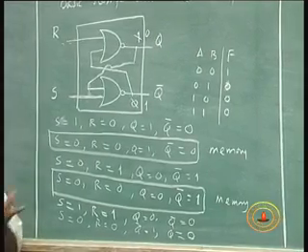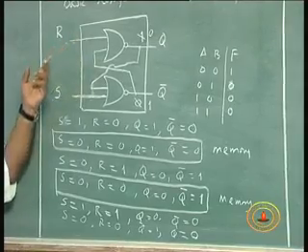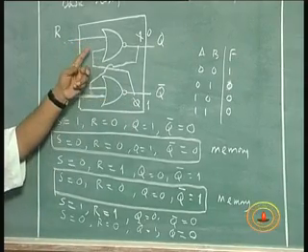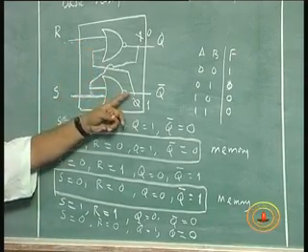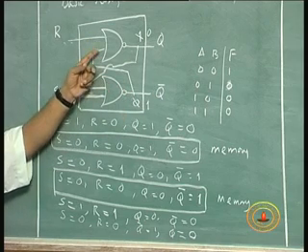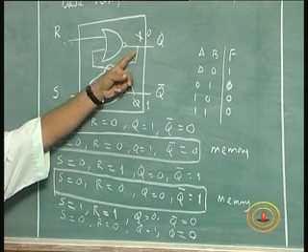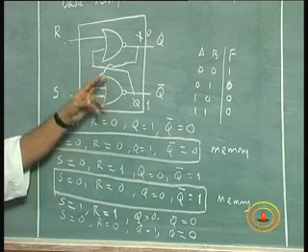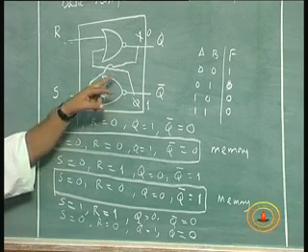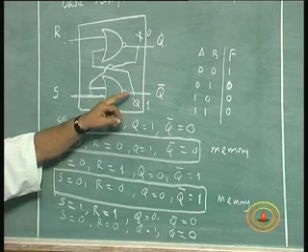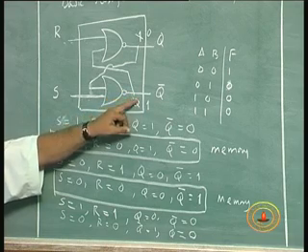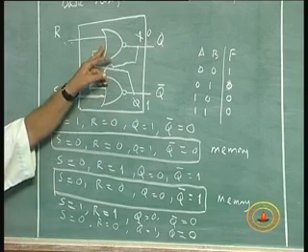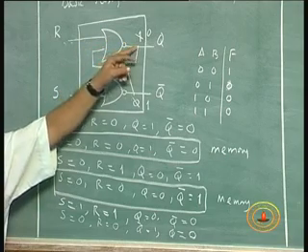On the other hand, if I started with this gate, this is 0 0, earlier output is also 0 0. So, this is 0, this is 0, this will result in a 1 here, that 1 goes here, 1 0, this is a 0. So, if I started my analysis with this gate first, I get a 1 here and 0 here.